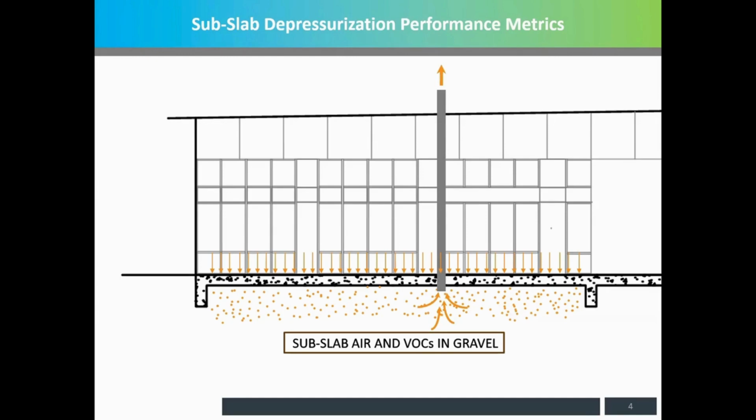For severed exposure pathways, the attenuation factor becomes 0. Or with SSDS, you might end up just attenuating the vapors. You can calculate that too, but we don't have time for the math. So again, we recommend checking out the workshop materials from AVIP 2025. Alternatively, many regulators have their own performance metrics for this. It could be 1 Pascal of differential vacuum, 4 Pascals, or 10.